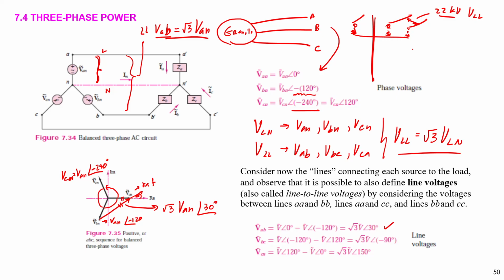Okay, and for this building, from the transformer into this building, we will have power of about 400 volts. This means line to line. And we have neutral, the line to neutral. V line to neutral is 400 divided by square root 3.